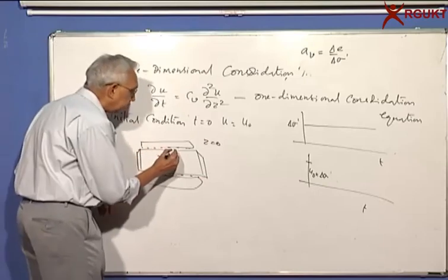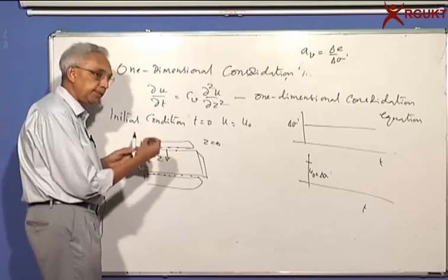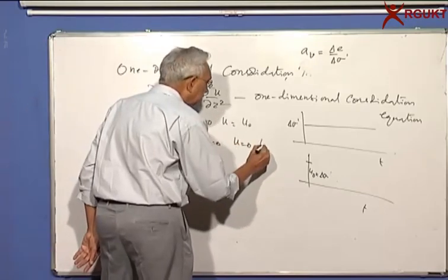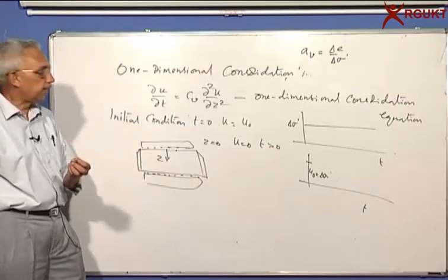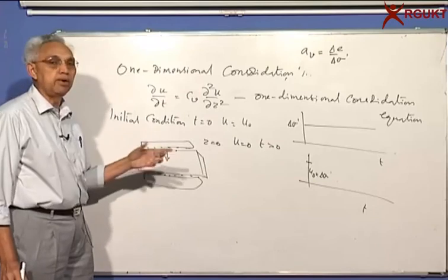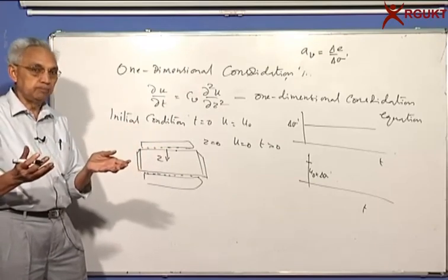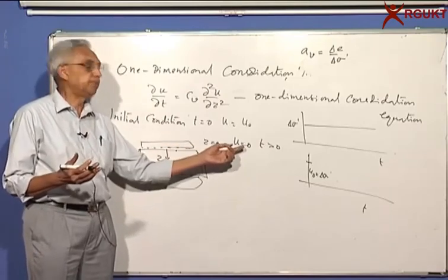So how long does the water molecule take to dissipate the pore pressure? It is at the boundary. So can I say that u is equal to 0 for t greater than 0? The moment consolidation starts, the pore pressure here will automatically become 0 because it doesn't have to travel at all. Once it dissipates, pore pressure becomes 0.